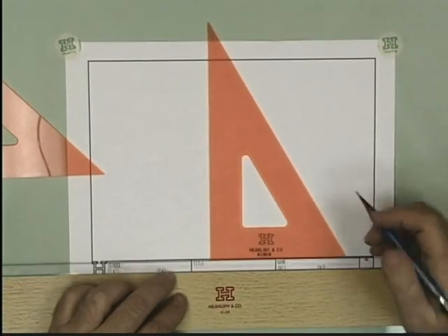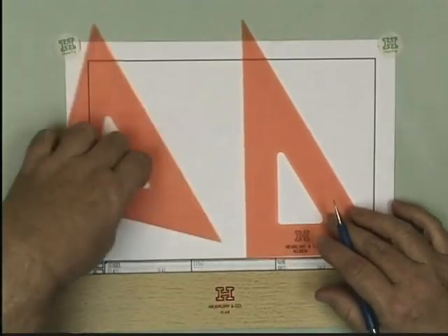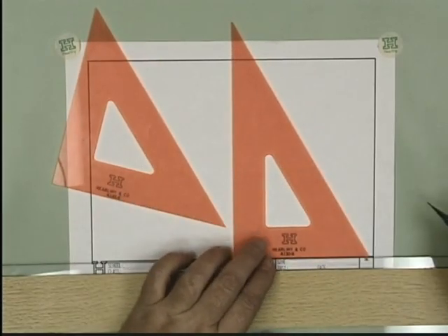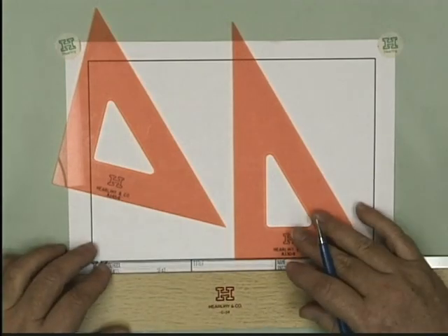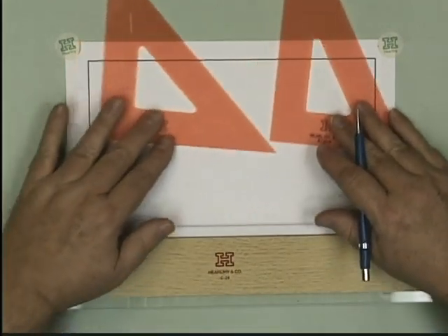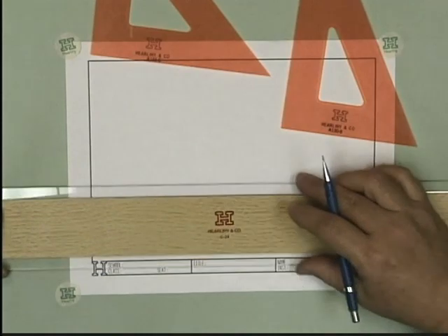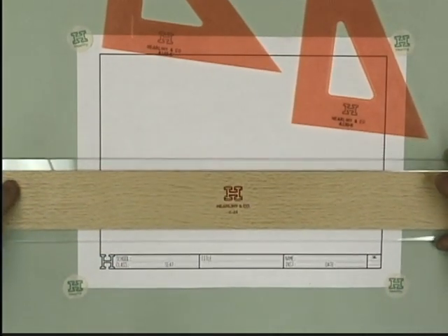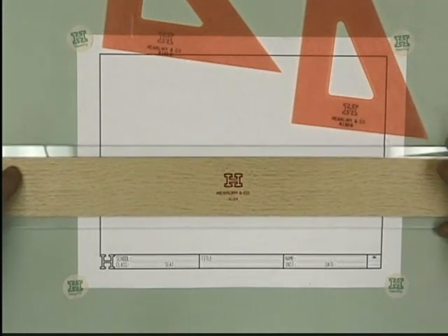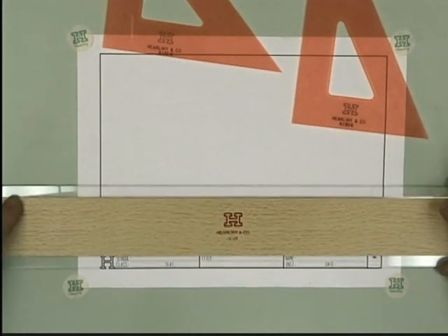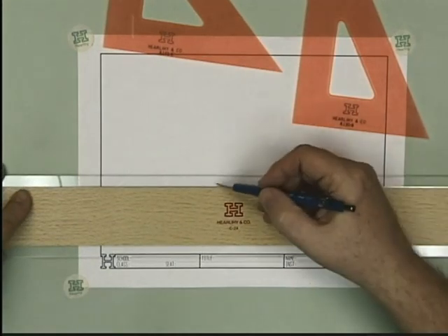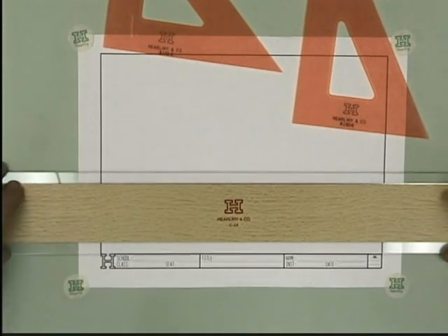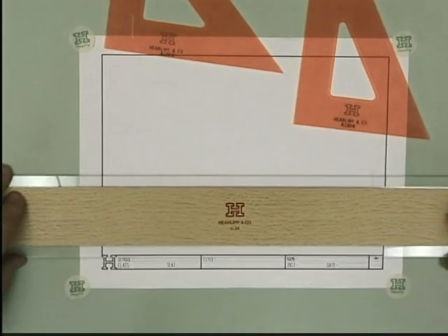It turns out in engineering drawings that these angles, 90, 45, 30, and 60, are very common. We can make all the horizontal lines on the drawing with the top edge of the T-square itself. I'm keeping the head of the T-square tight against the left edge of the drawing board so that as I move it up and down, that top drawing ruling edge, as they would call it, this is the ruling edge of the T-square, stays horizontal and makes parallel lines.